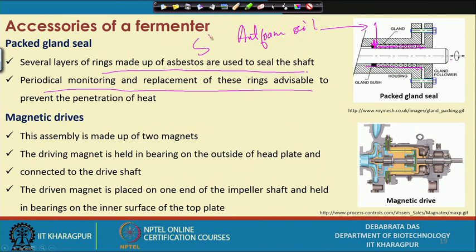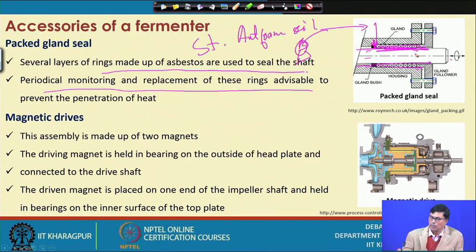And this is sterilized anti-foam oil with the help of a pump. We put it inside just to lubricate the shaft. If we lubricate the shaft, the friction across the mechanical seal will be less, and since we are passing at high velocity, there will always be a positive pressure, and if there is a positive pressure, no air can enter into the system.